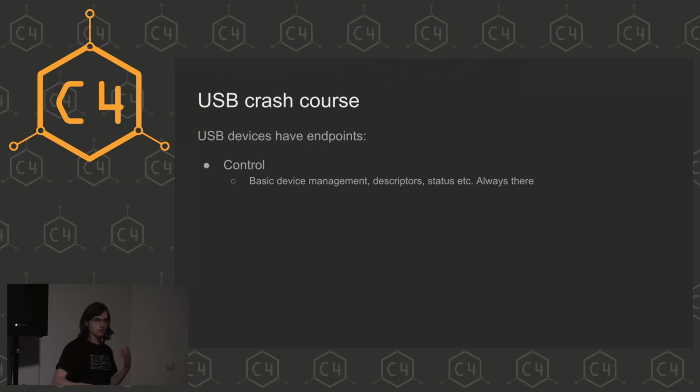the USB host stack is going to read some so-called descriptors, which tell the operating system what kind of device that is. Is that a mass storage device? Is that a USB serial adapter? Is that a switch? Whatever. This thing is always there. It has to be there per spec. So you always have a control endpoint.